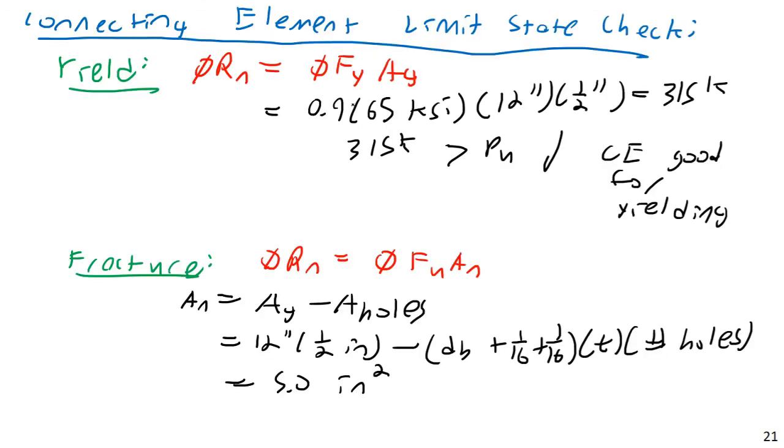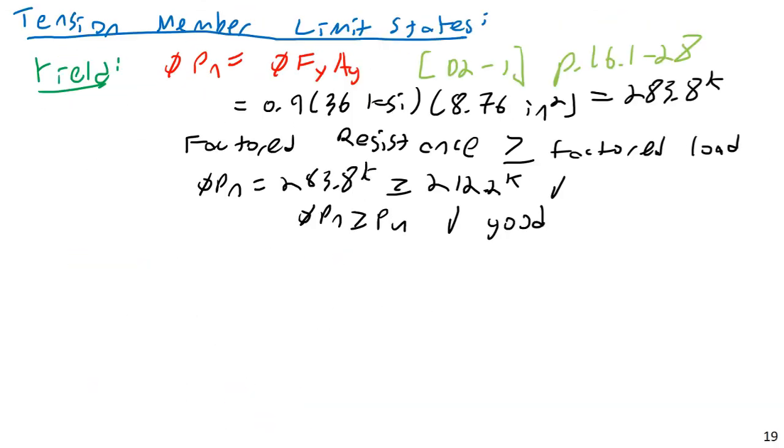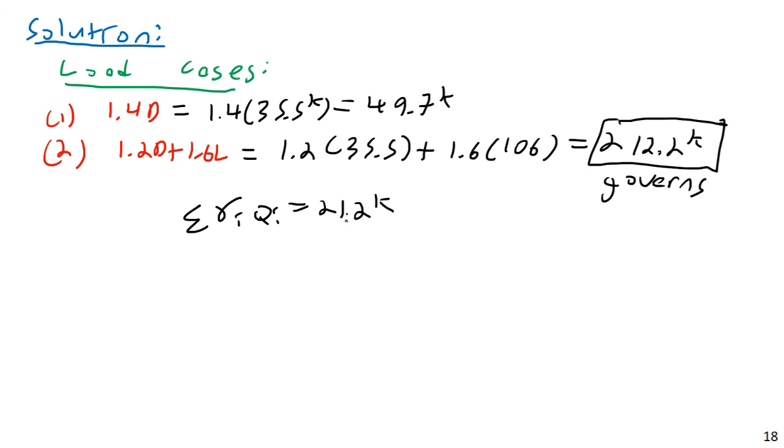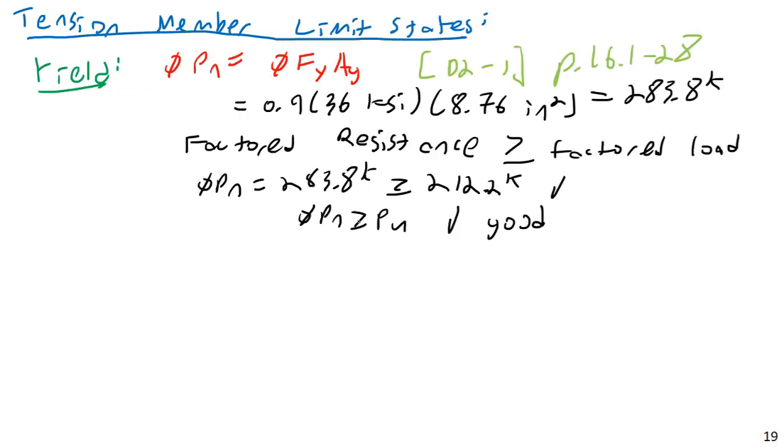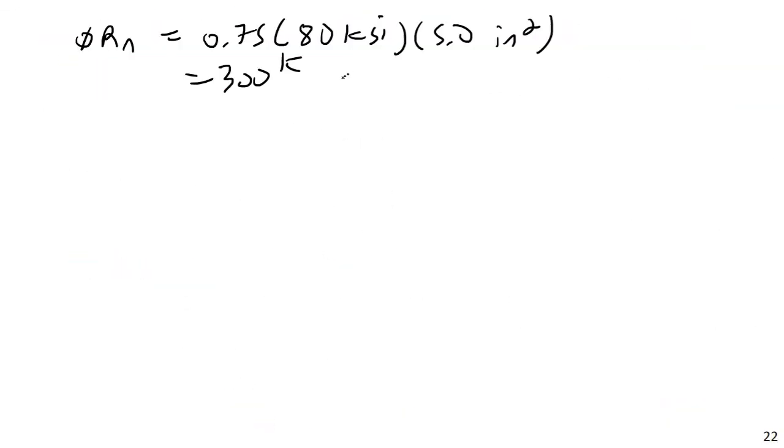And if we go back, we remember that in our loaded case we had an ultimate load of 212 kips. So this is much greater than 212 kips. So therefore, this is good in fracture. The connecting element is good in fracture.